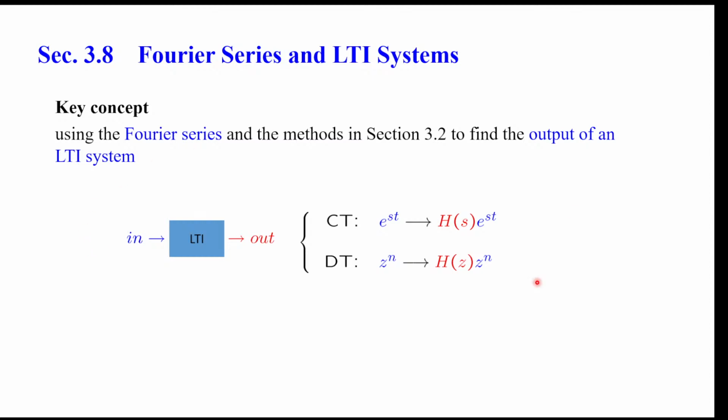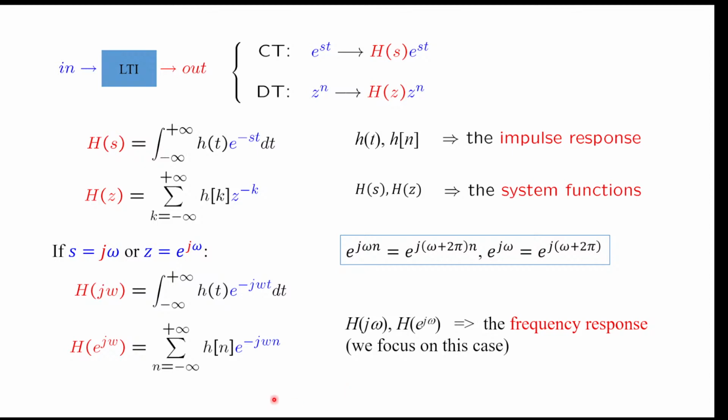So here's a bit of review. Remember that we want to decompose things into Fourier series because when we analyze the LTI system, those complex exponentials are eigenfunctions of your LTI system. So Fourier series was just for signals, and now we are getting back to our analysis of a system, in particular LTI systems. We derived those in the very beginning of this chapter.